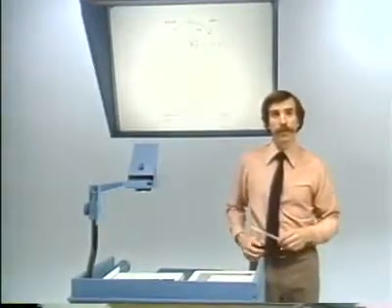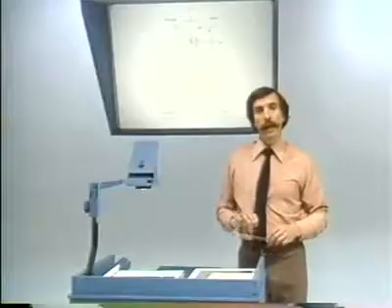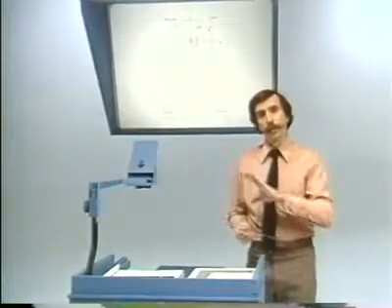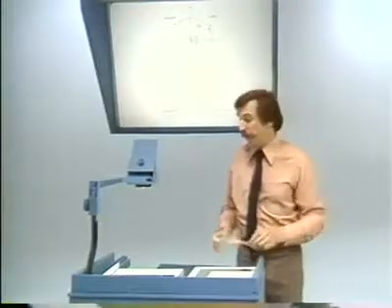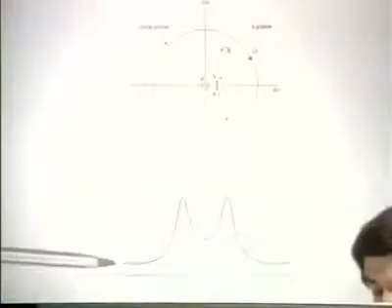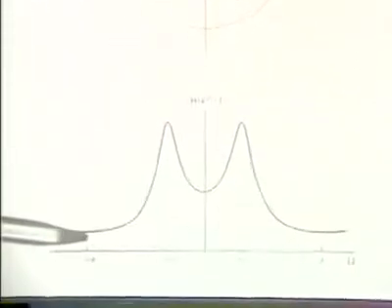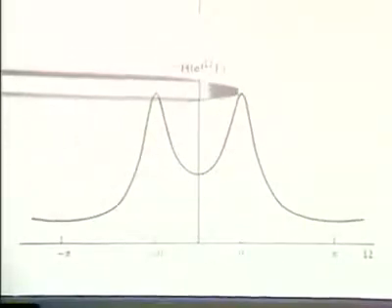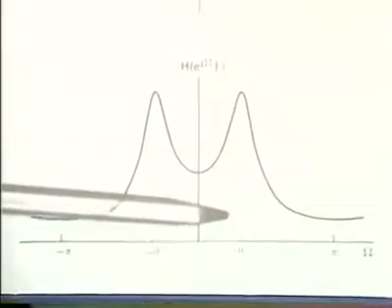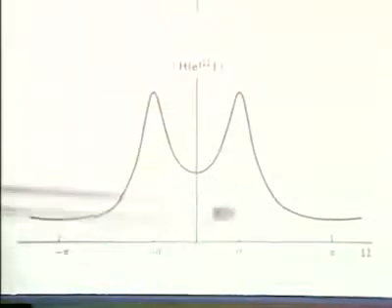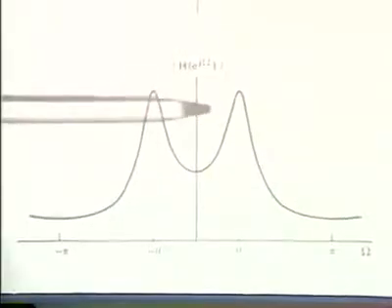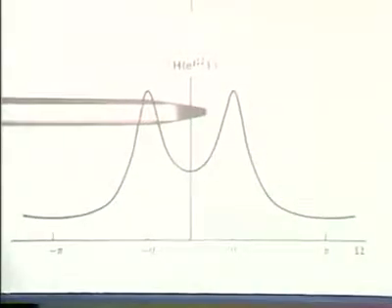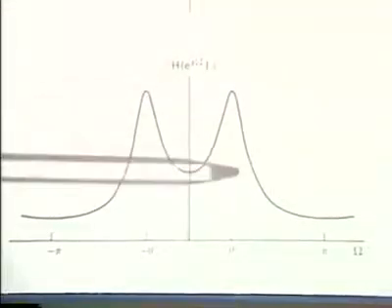Namely, we can evaluate the system function on the unit circle, and we in fact evaluated the Fourier transform associated with this pole-zero pattern last time. Recall that the frequency response is one that has a resonant character, with the resonant peak being roughly in the vicinity of the angle of the pole location. And as the parameter r varies, let's say as r gets smaller, this peak tends to broaden. As r gets closer to 1, the resonance tends to get sharper.